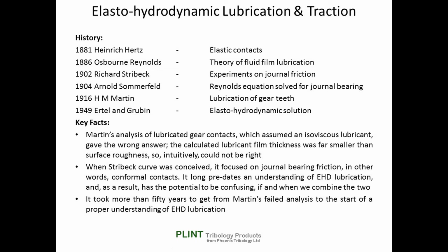The other point to note is that when the Stribeck curve was conceived, it focused on journal-bearing friction, in other words, conformal contacts. It long predates our understanding of EHD lubrication, and as a result, it has the potential to be confusing if and when we combine the two ideas. The final point to note is that it took more than 50 years to get from Martin's failed analysis to the start of a proper understanding of EHD lubrication.